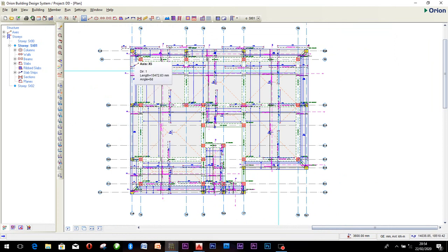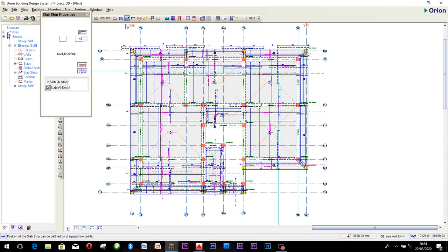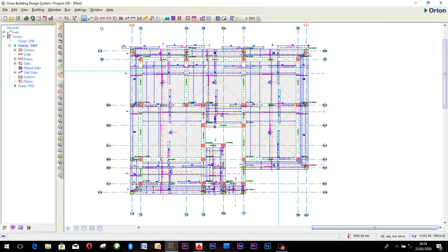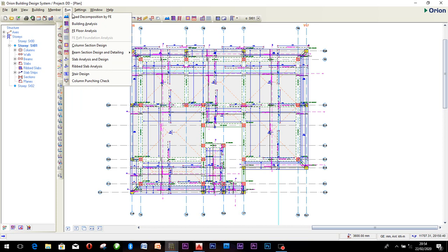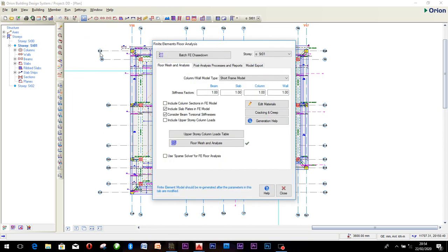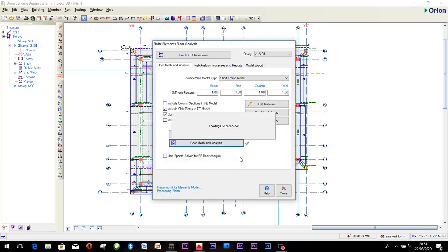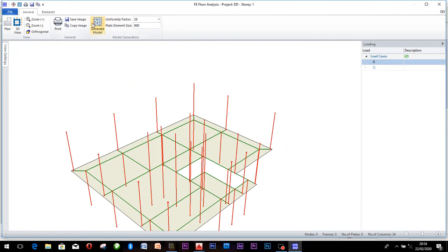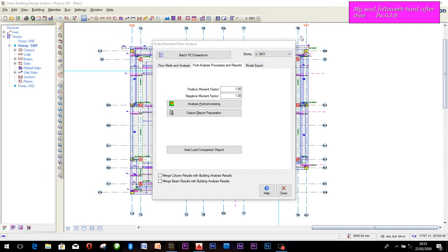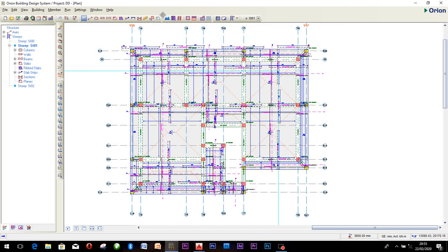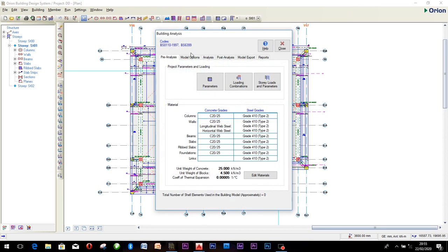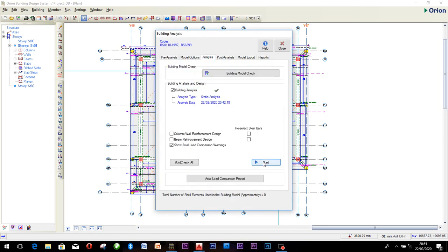Remember, we stripped from here. After stripping, what did we do next? After stripping, you go to fillet elements in run. Go to Orion to run and click on the fillet elements. And when you click on the fillet elements, you batch. That's the second thing we did. You close. Then after doing that, you click on your structural analysis, analyze, and start the analysis.